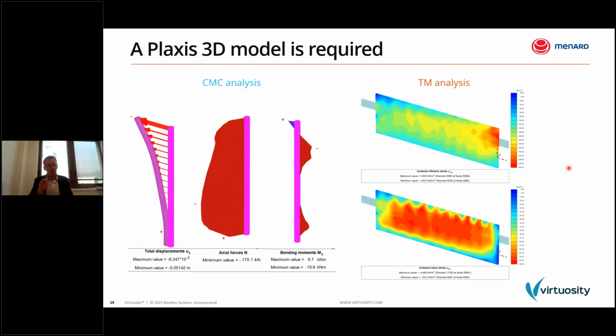So what we generally do is inside this volume element, we had a beam at the center, and we give this beam axial stiffness and flexural rigidity equal to the one of the CMC, but divided by a factor of 10 to the power 6, by a huge factor, in order that this beam does not impact the result.